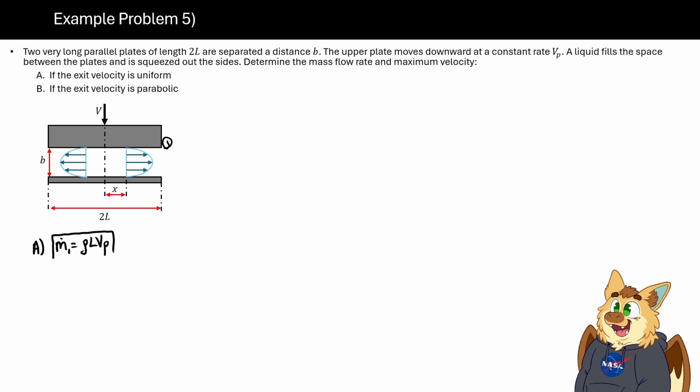And this mass flow rate, just to clarify, after we shrink our control volume down with time, the integral form of conservation of mass gave us how much total mass has to be flowing out through the vertical faces 1 and 2. And this is a global constraint. And it's something that has to be satisfied no matter what. That's what we had found from the conservation laws.